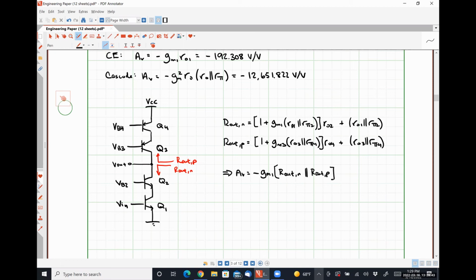So if transistors Q3 and Q4 were identical, except for the fact that they are obviously PNP transistors and not NPN transistors, and all other parameters were the same, what should we see the voltage gain of our cascode configuration fall to? How about that? So this guy with an ideal current source effectively represents the maximum possible achievable gain.